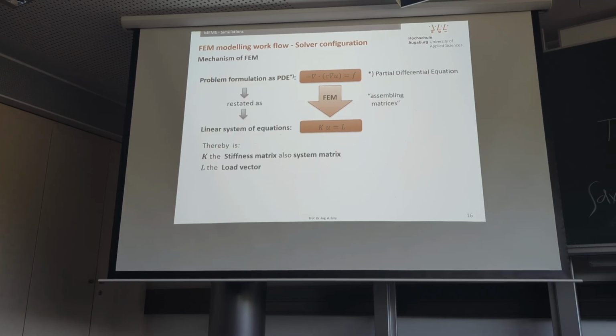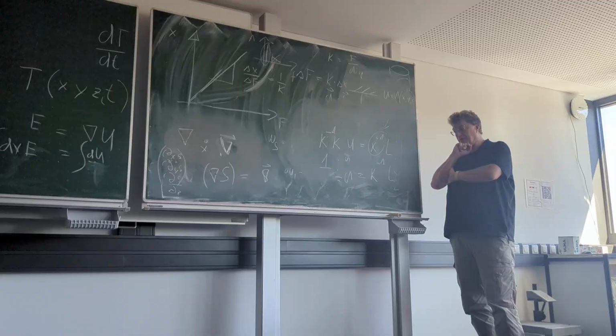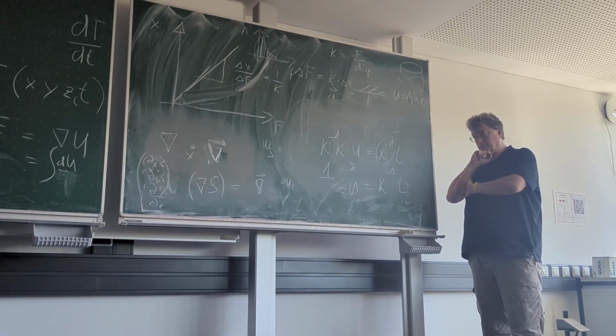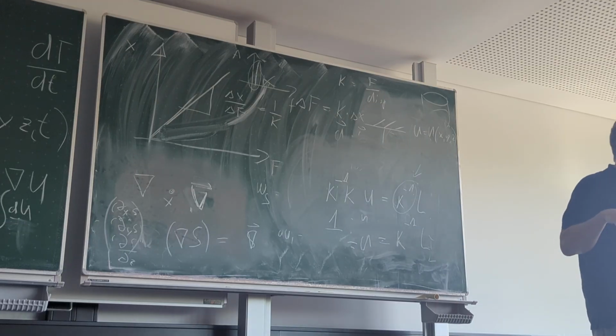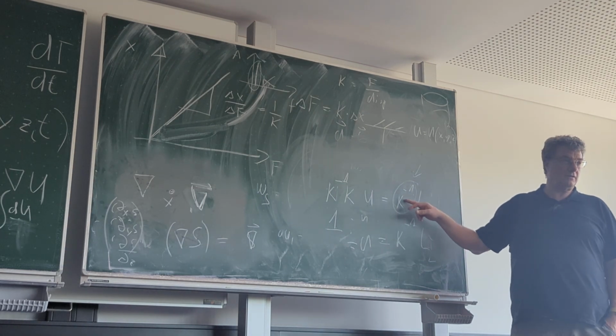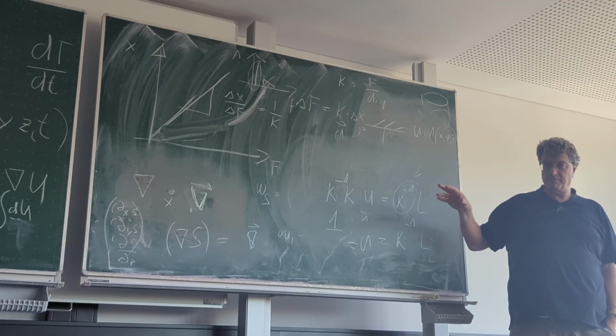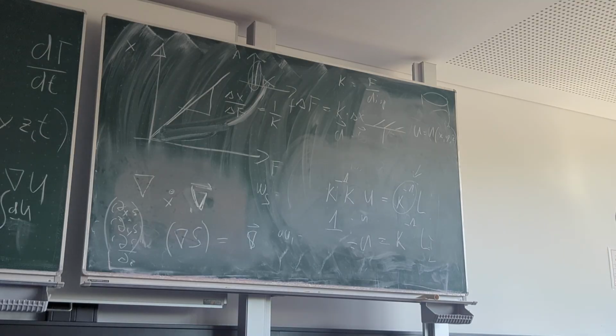Maybe also share this with you at that moment. The standard way COMSOL decides for the direct method is for 2D models. If you draw a geometry in 2D, then the corresponding matrices are usually, in most cases, small enough that the direct method can be used, meaning just let the matrix inverse. Then you have no problem with convergence, because that is just an algorithm. It takes a certain time. If you have enough memory, it works out.